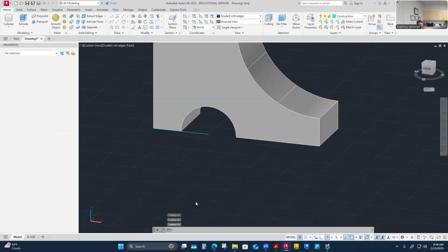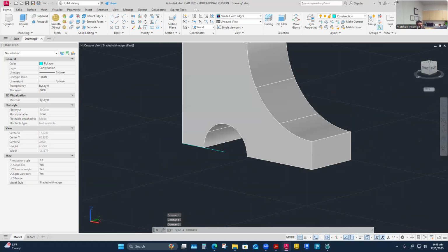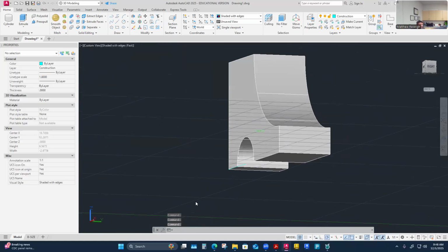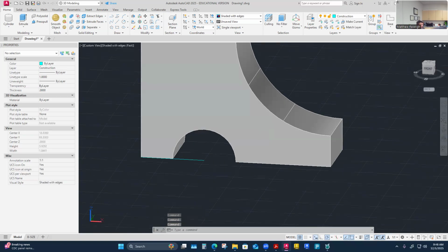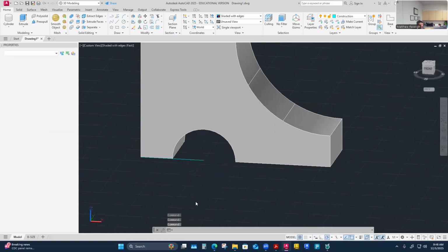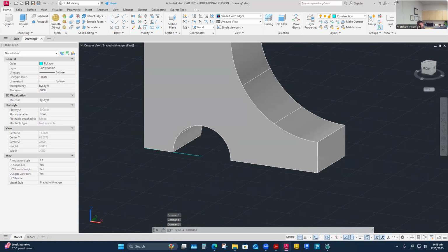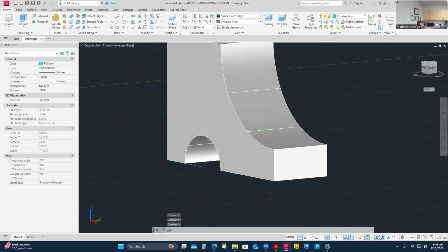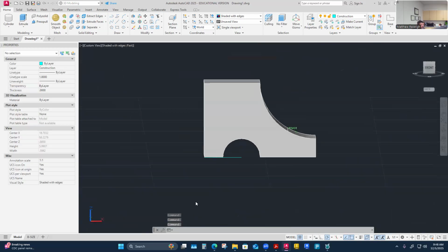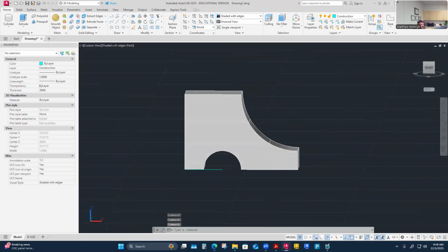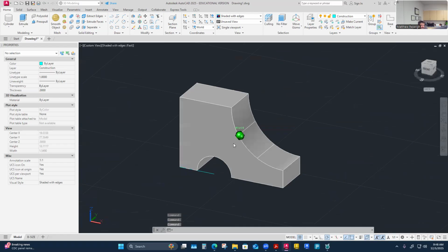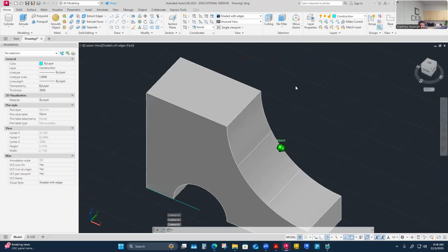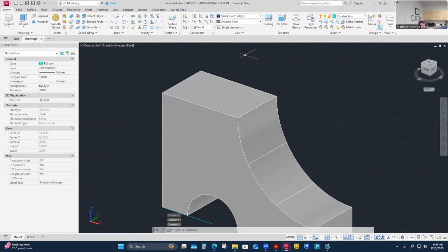Or if you didn't put that in, that's okay too. I just want to show you that you can 2D sketch on a face. So that is really related to Inventor, by the way. I'm going to use surface faces to do other 2D sketches. So that's a technique I'll use later. And so there's my boot. And then to get the top part, it's pretty easy because I've got the shape of it here. So I can actually just choose to extend this up.